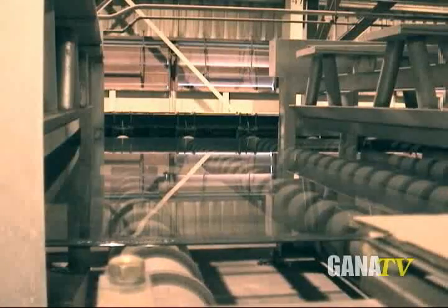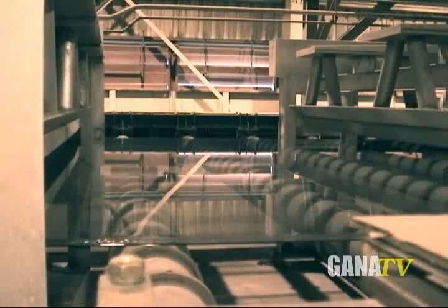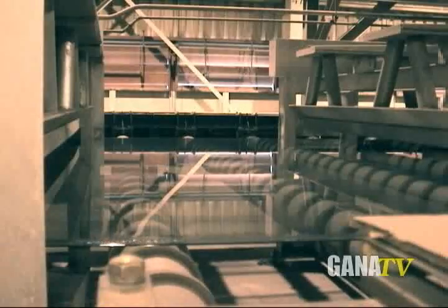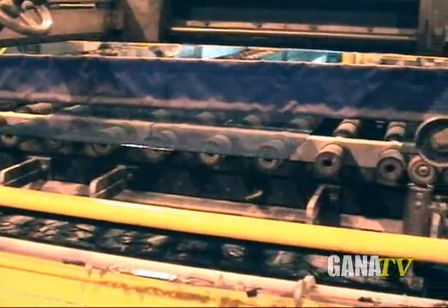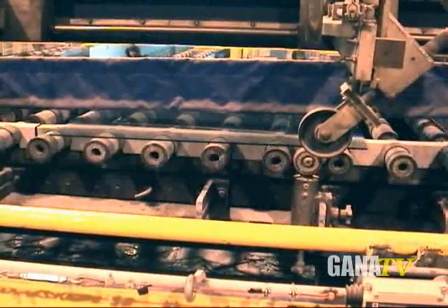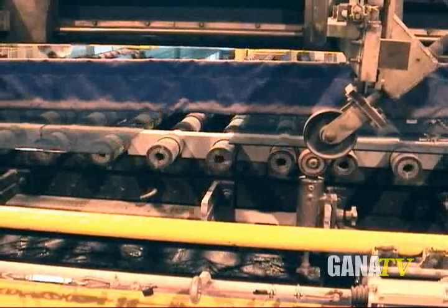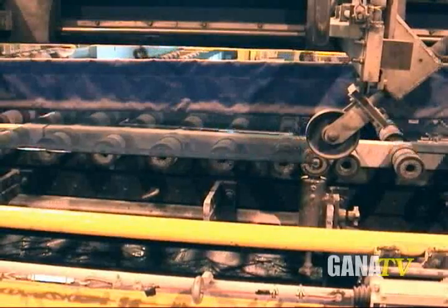At this point, the glass is uniform, with only the indentations left by the top rollers remaining to be removed later in a process called edge trim. The excess glass removed in this process is carried back on conveyors to be reintroduced as cullet into the melting process at the beginning of the line.